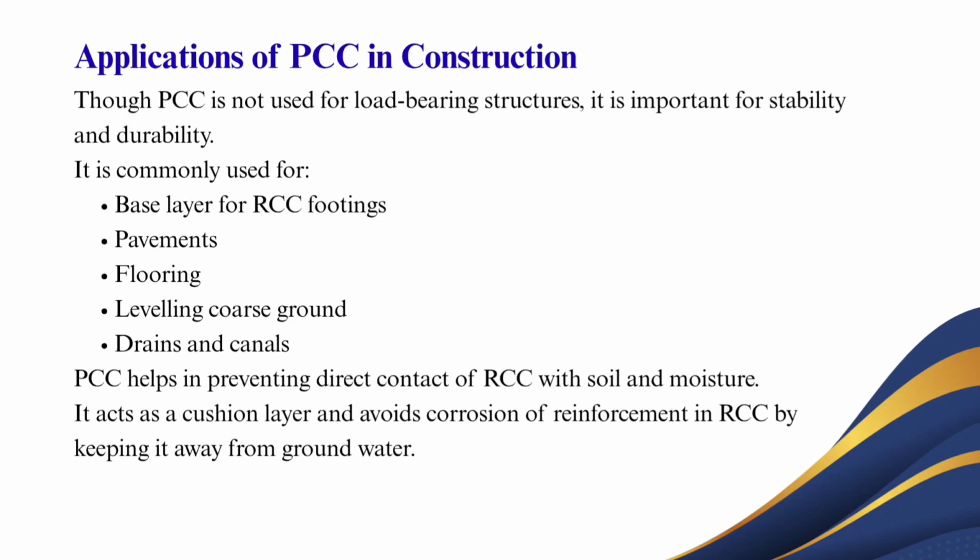Though the PCC is not used for load bearing structures, it is important for stability and durability. It is commonly used for the base layer of RCC footings, pavements, flooring, leveling coarse ground, drains and canals, etc. So the PCC helps in preventing direct contact of RCC with the soil and moisture, and it acts as a cushion layer and avoids erosion of reinforcement in the RCC by keeping it away from the groundwater.